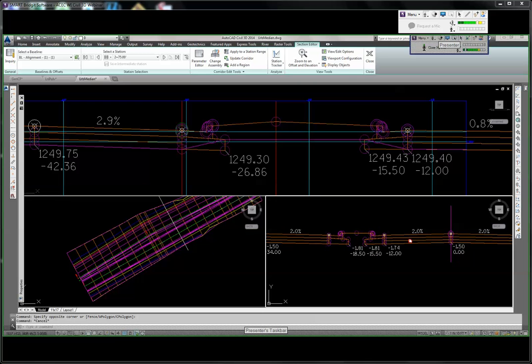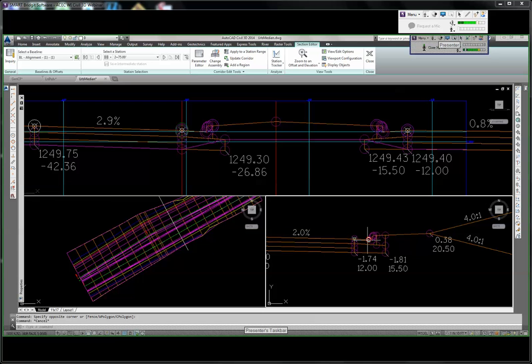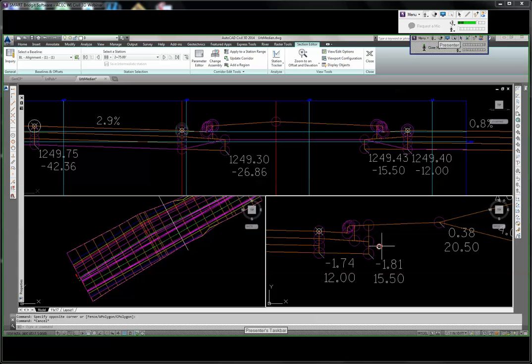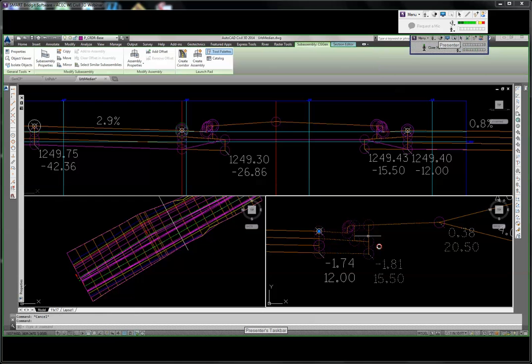And finally, I'm going to use this assembly to look at the curb and gutter, the CG Gen subassembly. Like I said, it looks somewhat similar to what we had for the urban median, but we've got some other things in here. If I highlight on it, I've got the curb and gutter, the subbase material extended, a portion here that is the top material above the subbase extension, and then a terrace area here. Now, the terrace area measurement is actually happening from the back of the curb. This is something that's easily missed. Some people measure or assume the measurement is from here, and they get an erroneous measurement because it's from the back of curb.